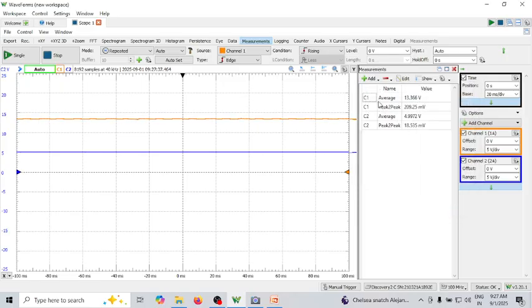Carefully note the input average is 13 volts, with a peak to peak variation of 212 millivolts. The output average is 4.9981 volts, almost 5 volts, and the peak to peak variation is hardly 14 millivolts. It's fairly constant at 5 volts even though the input is varying, because the input voltage is always more than 7 volts.